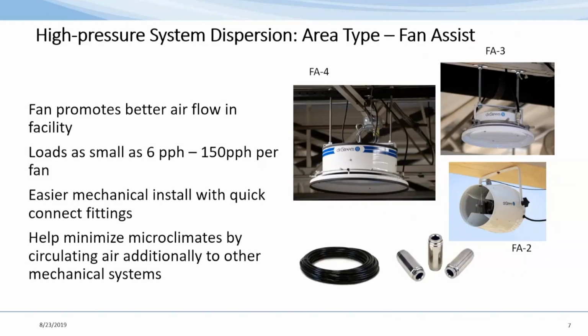Typically with FA3 and FA4, we're pulling the hottest air from that facility down through this fan and then providing the mist at that place. There's capacities listed on the screen regarding what our offerings can be, and there's 3 models. And where that capacity differs is based on the ceiling height to the lowest item in the room and different size pound per hour nozzles.